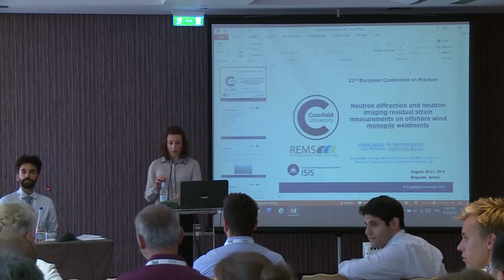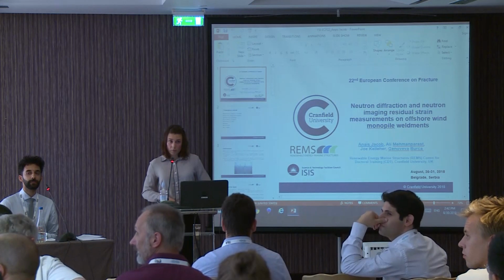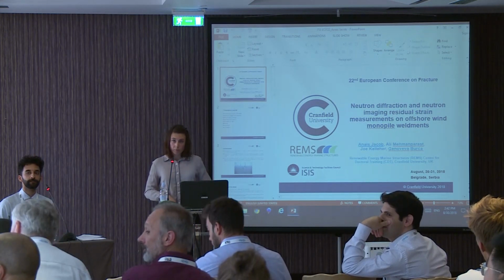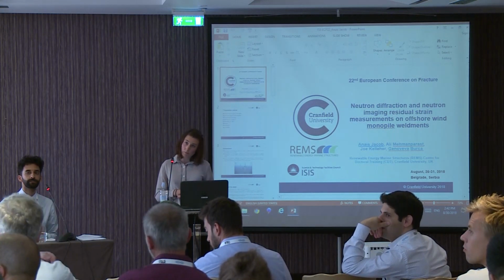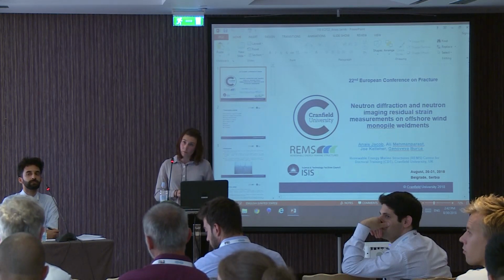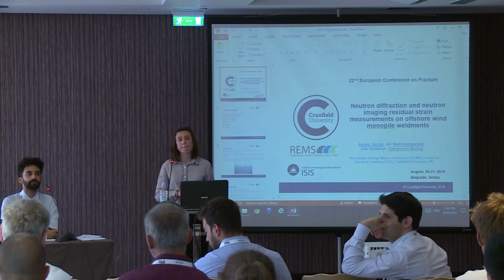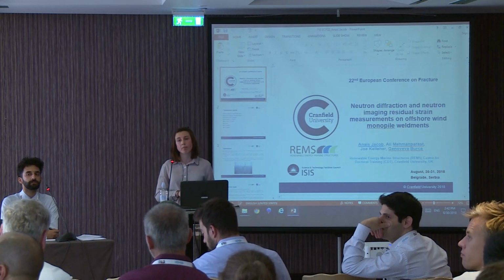Your question? Yes, please. I want to ask a small question. Normally if you cut a specimen from the big specimen, then the stress is really skewed. So the relief of the residual stress needs to be considered in your measurement. In your case, have you thought about this problem, or do you just want to measure the CT specimen?